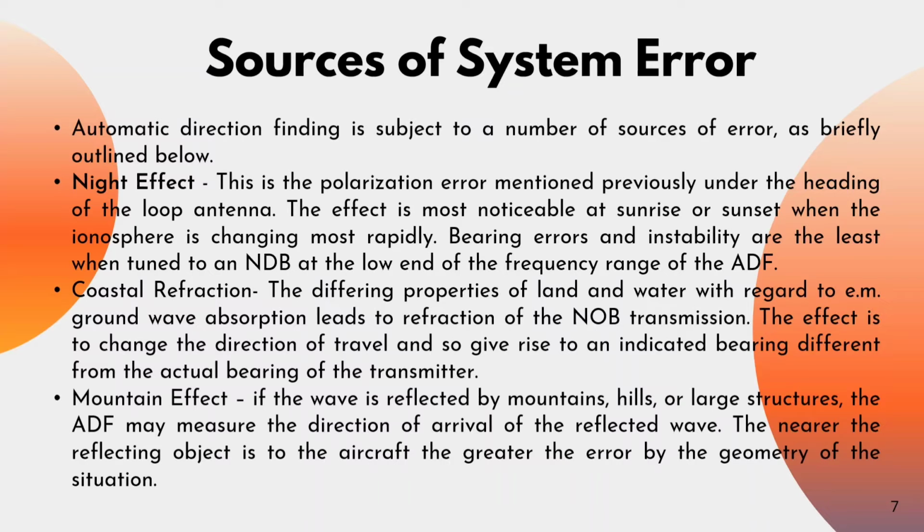Coastal refraction. The differing properties of land and water with regard to EM ground wave absorption lead to refraction of the NDB transmission. The effect is a change of direction of travel and so gives rise to an indicated bearing different from the actual bearing of the transmitter.